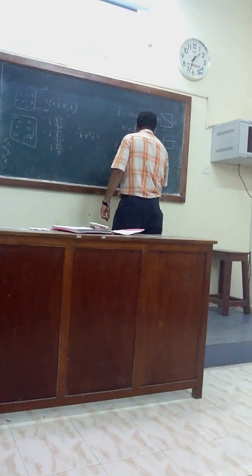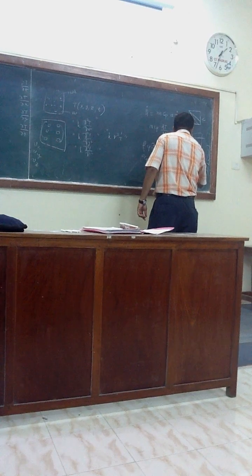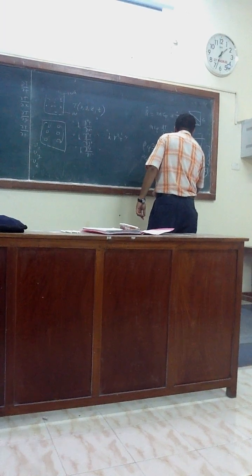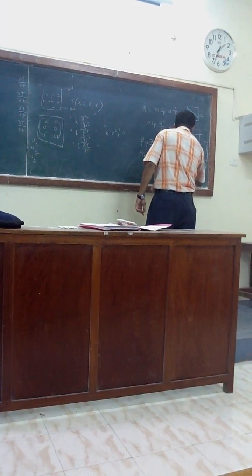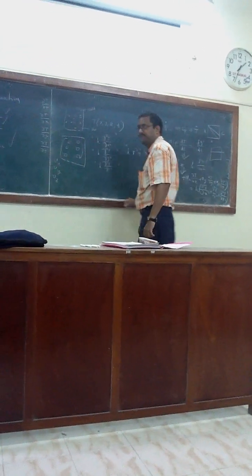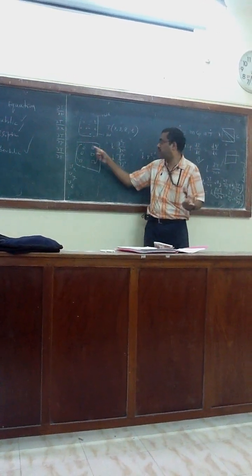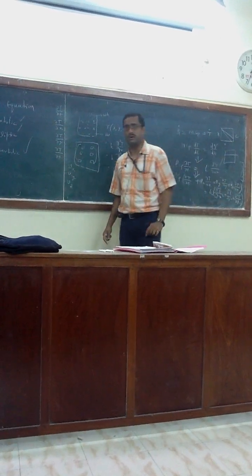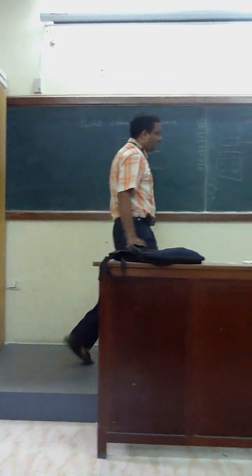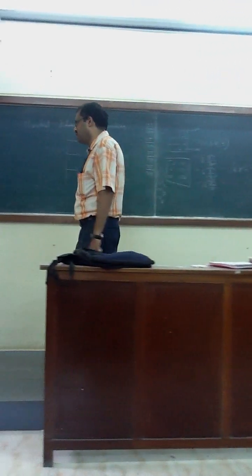So that will be taken as Vx ∂T/∂x plus Vy ∂T/∂y plus Vz ∂T/∂z equals K times ∂²T/∂x² plus ∂²T/∂y² plus ∂²T/∂z². Correct? So this is your sensible heat. This is for the fluid particle moving and this is for the thermal conductivity transfer. I am assuming there is no heat generation, no Bunsen burner. So this is a very philosophical way to look at the energy balance equation.